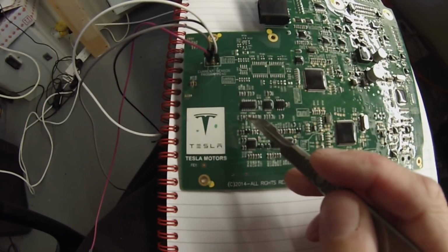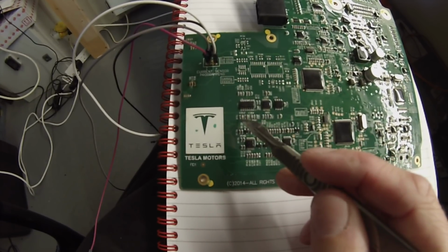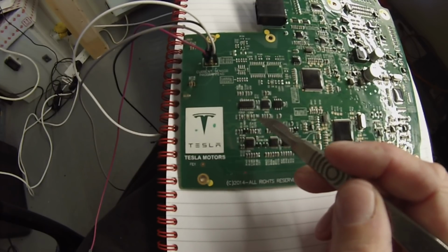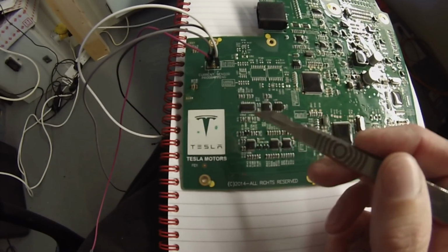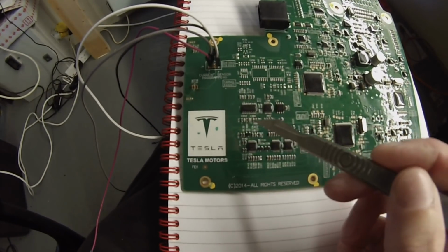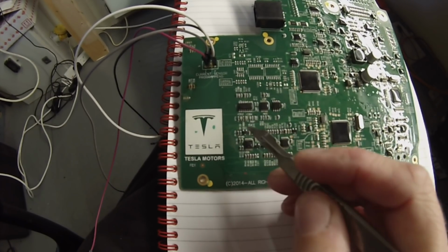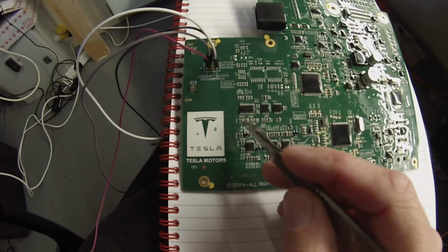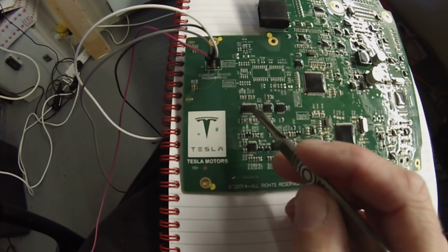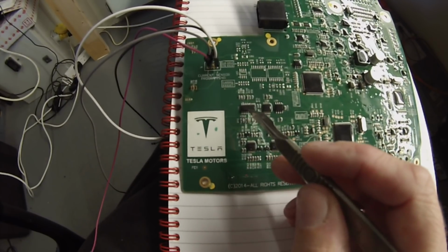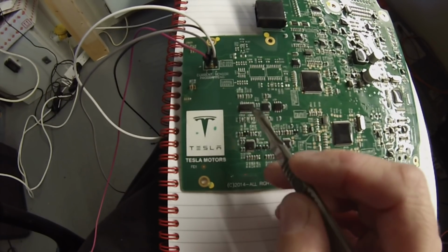And these resistors here, so these ones from R70 over to R98, are used to divide the input from the current sensors by slightly less than half. There's a 10K and a 12K resistor that are used. And this buffer amplifier then basically prevents any loading on the current sensors.